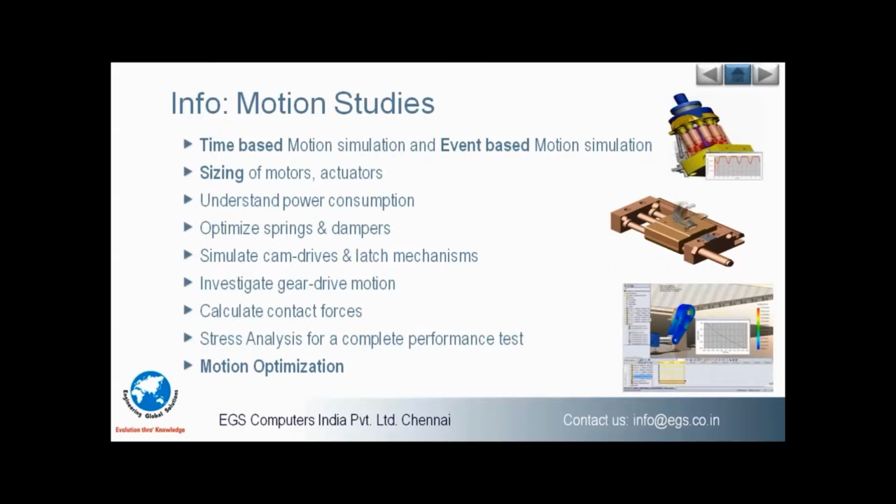This motion study can be done by either a time-based motion or an event-based motion by moving the time bar, which has been shown in the figure. Using the motion study, we can study how many motors I need or how many actuators I need, and you can even size the motors and the actuators. By this, we are going to understand the power consumption of our assemblies.